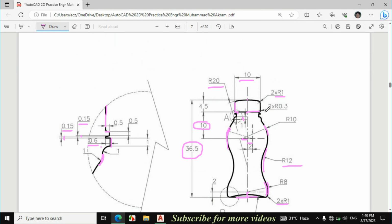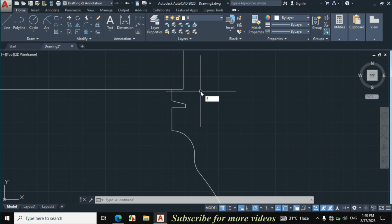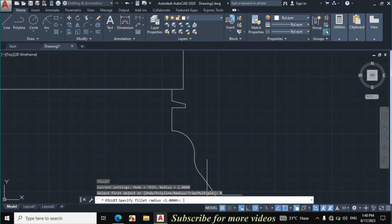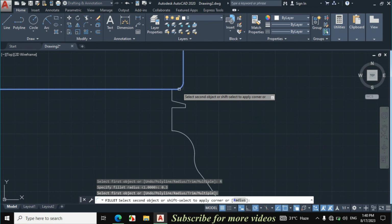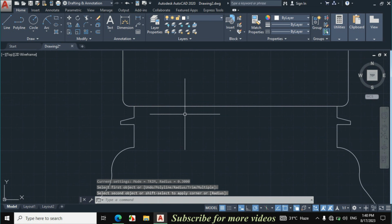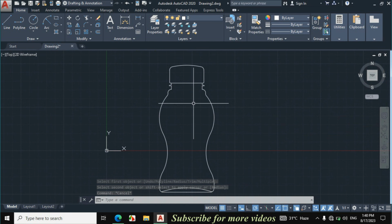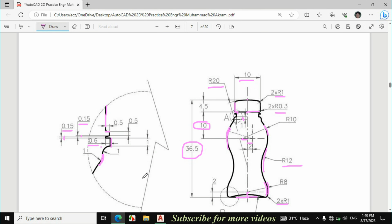which is 0.3 mm. Let's make this fillet radius. F, enter from the keyboard, click on radius, enter 0.3 mm fillet radius, click on this line, click on this, press space to repeat the command, click on this line and click on this line. Now this figure is exactly made according to this dimension.